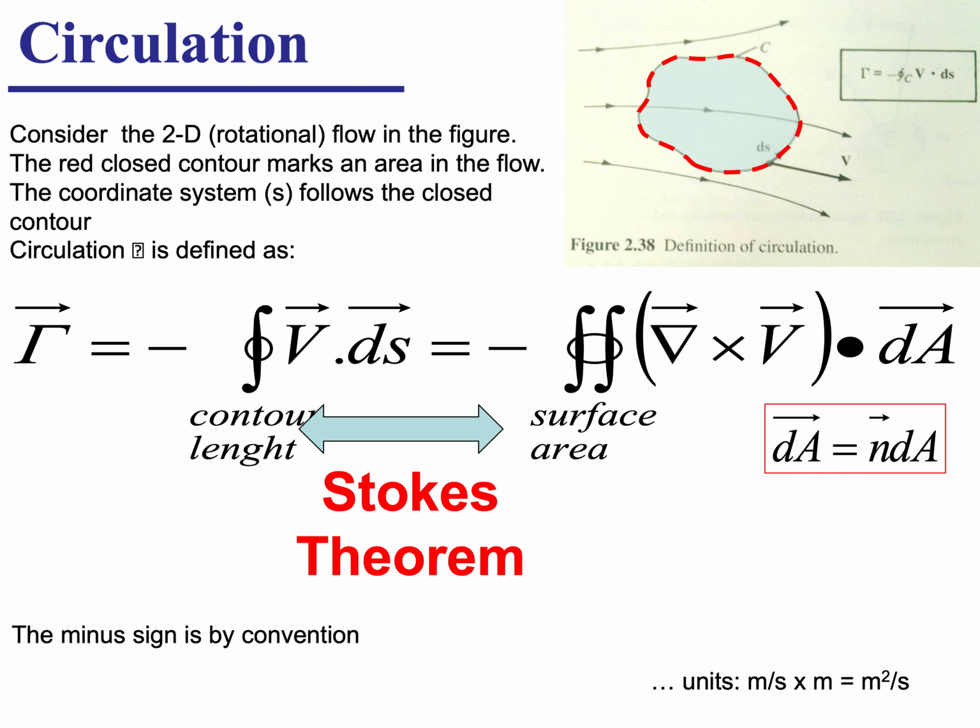this is a snapshot in a region of the flow, and these are our streamlines, then I can pick any region inside my flow. So it could be inside the boundary layer or outside the boundary layer. And I want to see how much rotation there exists inside this large region. So in that region, I can just take all the fluid elements. So I break it into an infinitely large number of fluid elements, and each fluid element might have a vorticity or an angular rotation around its axis.